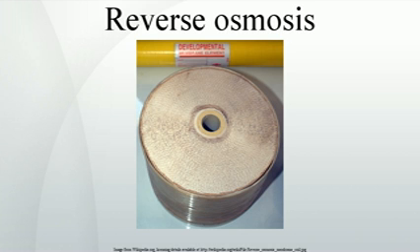Drinking water purification. Around the world, household drinking water purification systems, including a reverse osmosis step, are commonly used for improving water for drinking and cooking. Such systems typically include a number of steps. A sediment filter to trap particles, including rust and calcium carbonate, optionally, a second sediment filter with smaller pores,